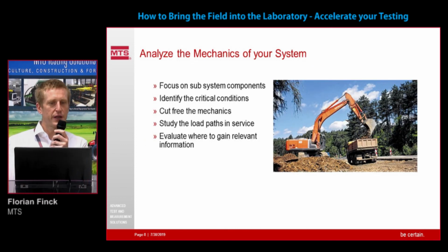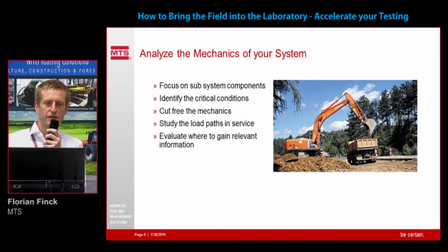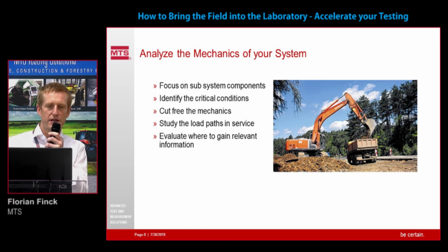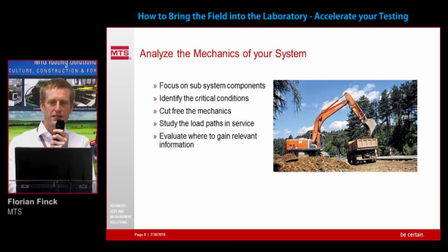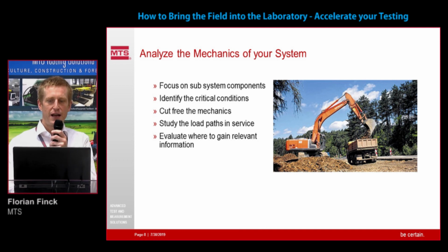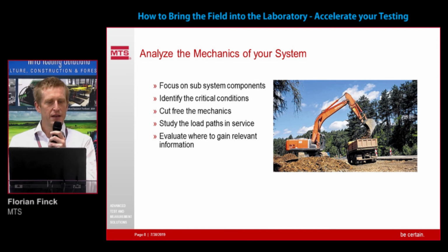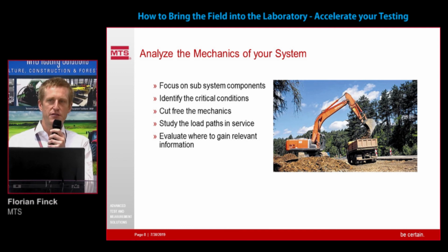The first step you're doing probably is analyzing the mechanics of the system. Take this excavator as an example, focusing on the lever arm of this excavator: what are the critical conditions? You can cut free the mechanics. You have a bearing here, you have a lever arm, you're moving a mass around, you're lifting it, you're turning the arm. So what is the load path in your structure? You have a finite element model that describes these typical loads.